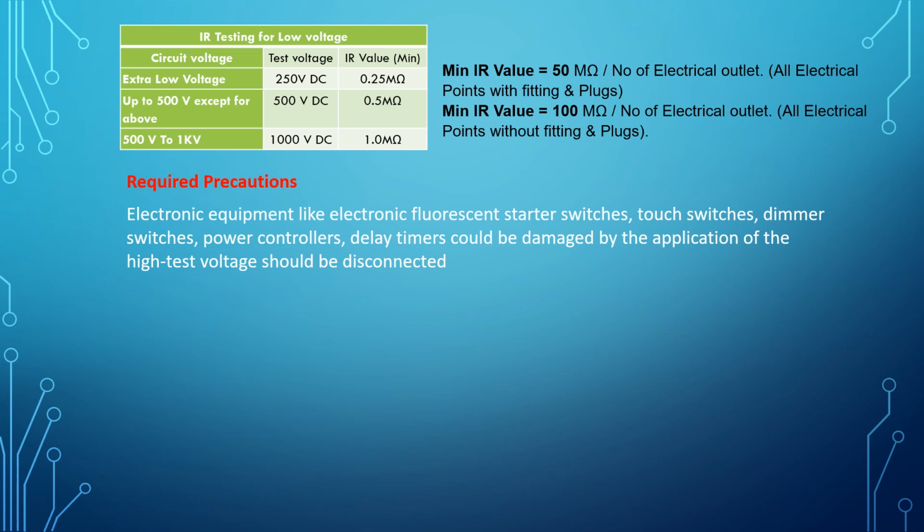Just to give you a sample from experience as well. We have a battery, for example, our sensor battery that's connected to our fuse holder junction box, and then that is connected to our controller. The value of the wire is 0.5. It's very small, 0.5. So you cannot do the testing because it will damage our cable. So that's why you need to do only the continuity test.